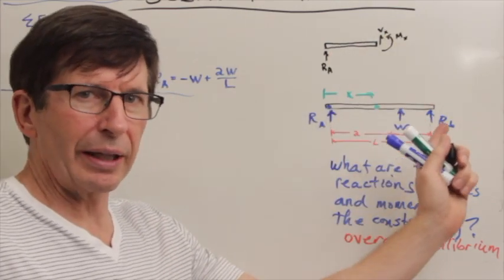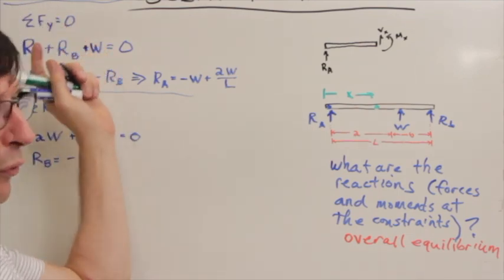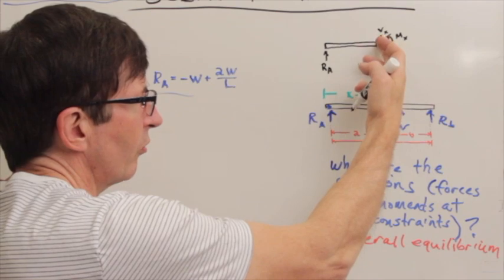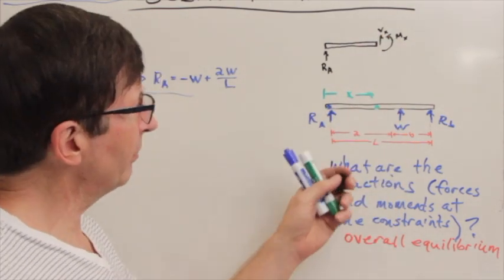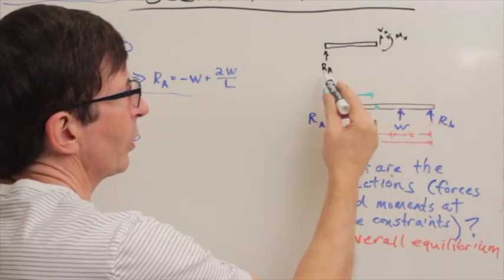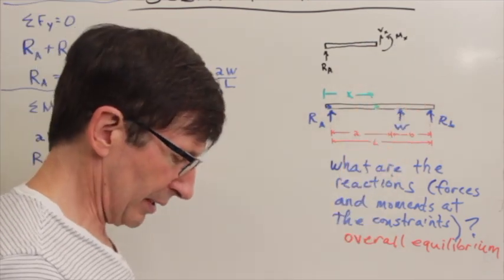I didn't bother to write F because there are no forces in the x direction to sum up. I know that there's no force acting in the x direction because then we would be violating equilibrium. So we're left with this shear force to counter RA and this moment.